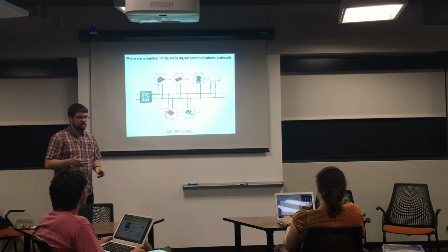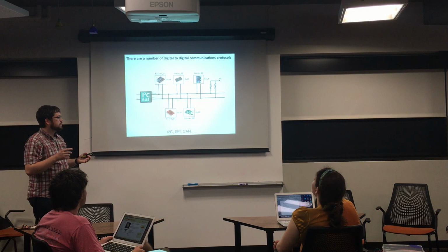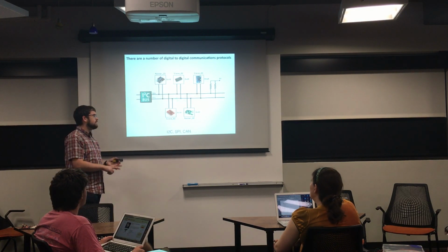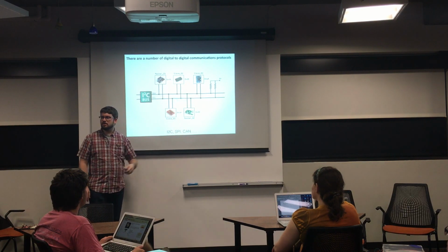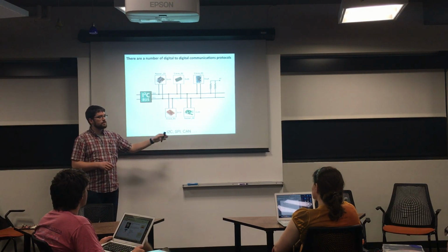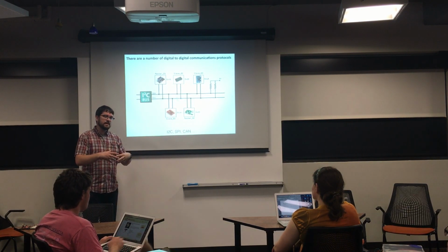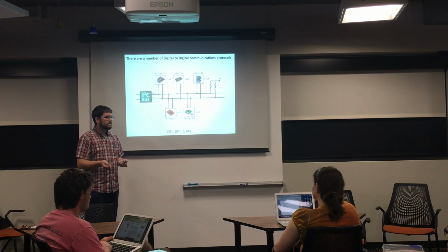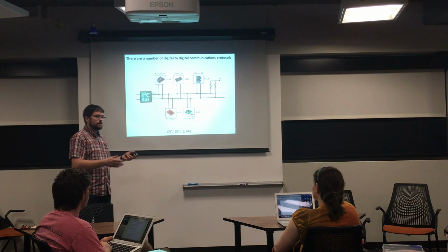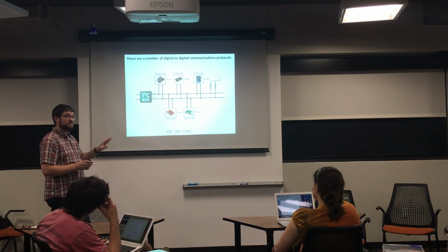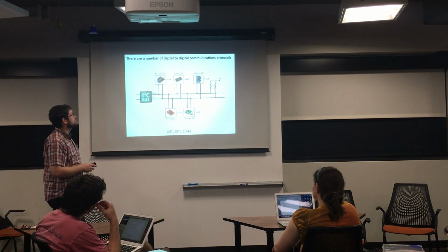There are a lot of these different interfaces out there. There's one called I2C, SPI, and CAN. CAN is the one that's used in cars. It stands for Controller Area Network. Everything on your car is connected to the CAN bus. That's how somebody can break out your taillight, connect to the CAN bus, and start your car through the taillight socket. So there are advantages and disadvantages to having everything on one bus.